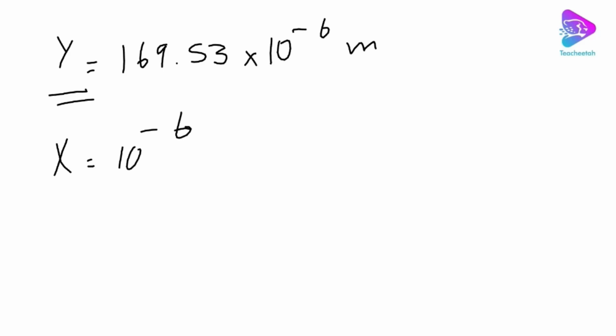So as you see, x is much smaller than y because we have a spring and damping in the system and make sure that it works as an isolator. So with this amplitude of base, we have this amplitude x of the grinding machine. We need to make sure that y wouldn't go beyond that when we have a floor vibration. For example, we can control the floor vibration by shutting down the source of vibration or reducing the source of vibration, or designing other materials or cushions for the machine.